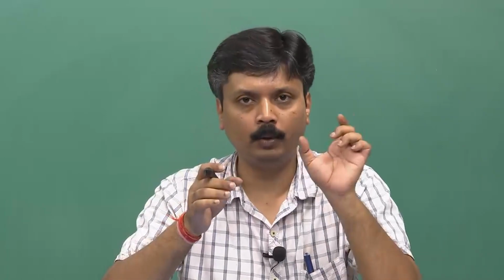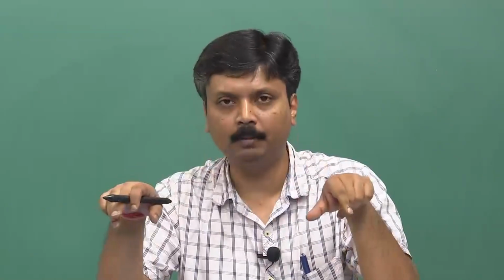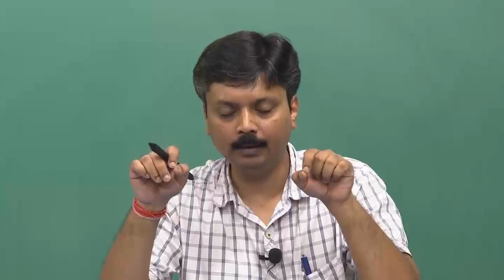So, you know nu, you know how nu is related to the cavity length, and then what is the difference between say nu 1 and nu 2. So, knowing that gap and knowing the overall spectral bandwidth of your laser active medium, it is extremely easy to find out how many such modes will be there. Okay. So, that is all we did.